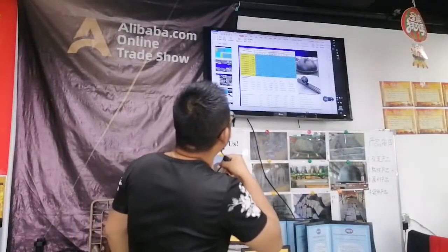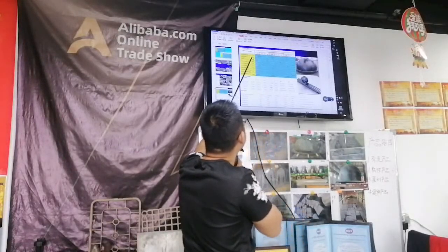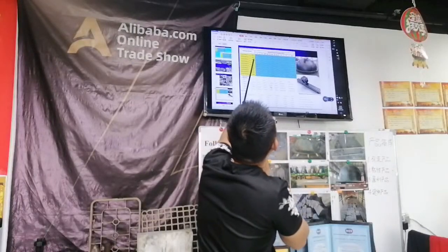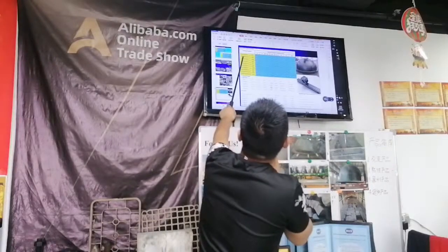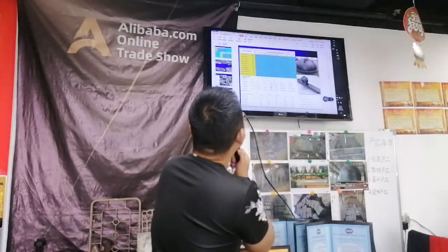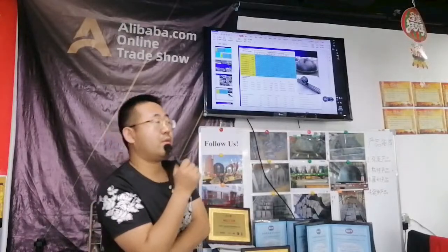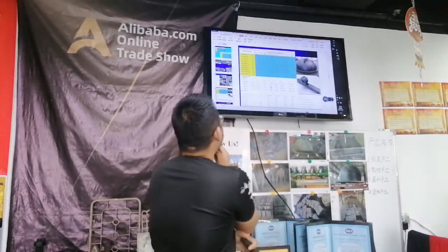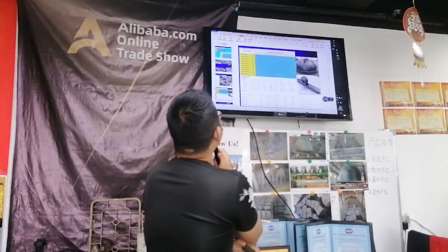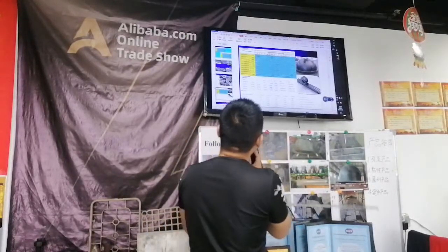This material includes 1.4823 and 1.4825, and 1.4825 is more popular, similar to SS304, which includes 18 chrome and 8 nickel, like this list.